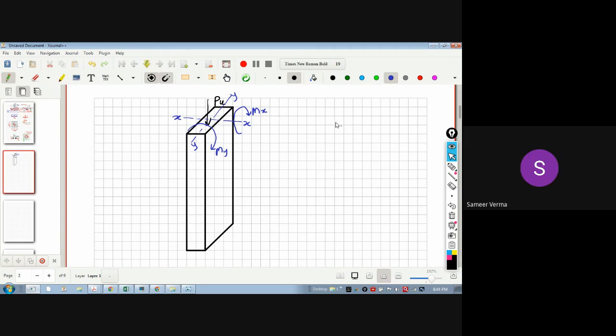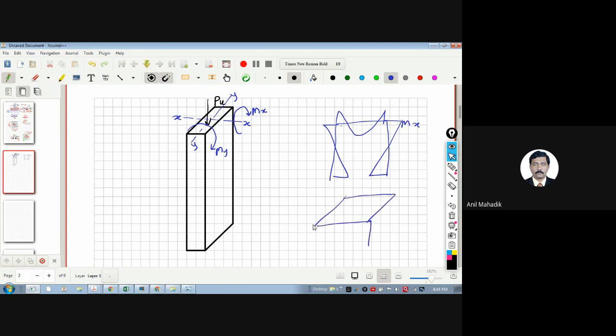We have, in 3D model, you might have seen. So this is your bending moment on the beam due to this. ये bending moment है हमारा समझो mx, and if this is a 3D building, then we get biaxial moment. तो ये ऐसे भी moment आएंगे, and there will be moment in other direction, ऐसे कुछ तो mx and my, you know it. So these are the bending moments in the column, mx, my, and axial load on the column.